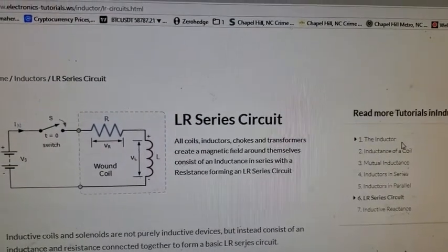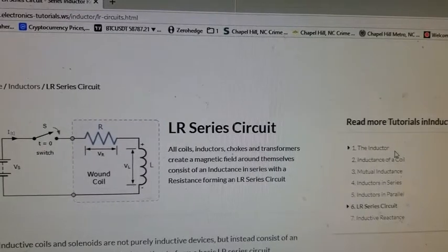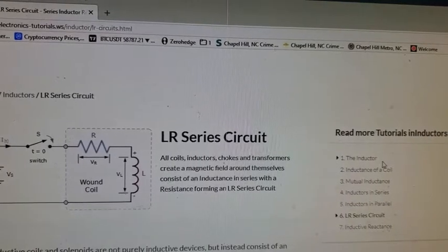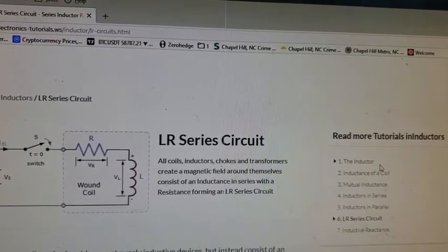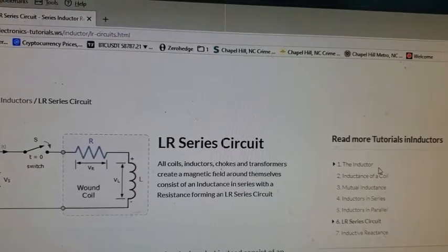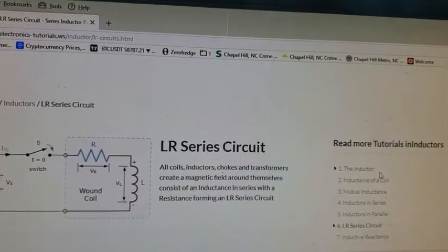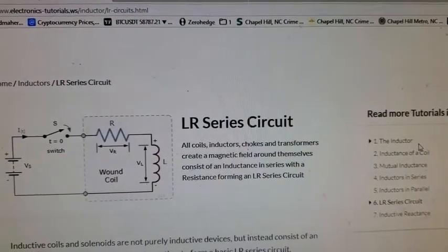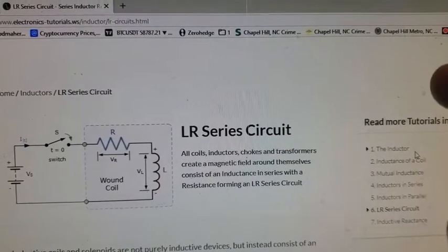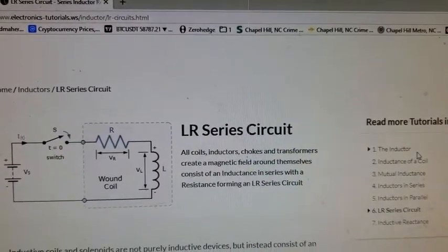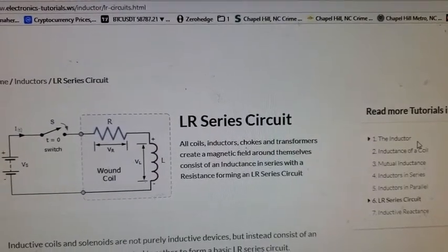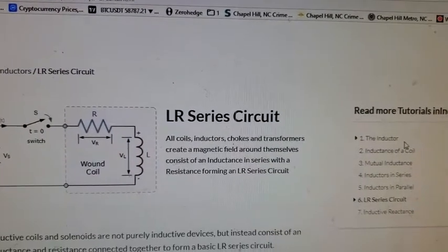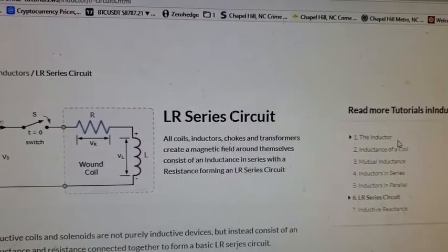The first is Faraday's law of induction, which states that the magnitude of the EMF, electromotive force, established is directly proportional to the rate of change of magnetic B field strength. So this total change in the field is termed magnetic flux. It's magnetic flux per unit time that determines the establishment of the EMF, and the EMF is what determines the magnitude of the inductive spike and the current that flows therein.